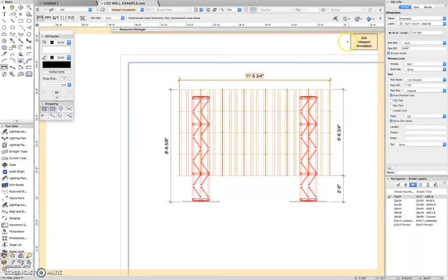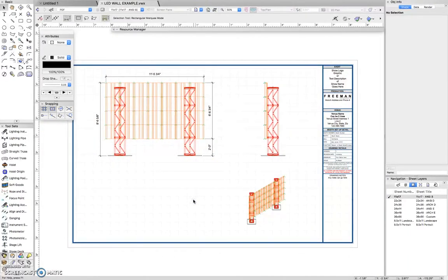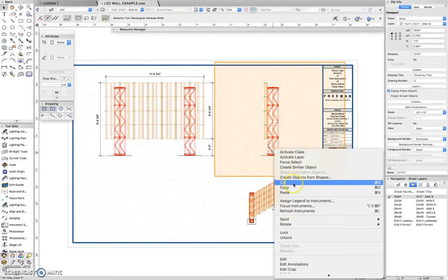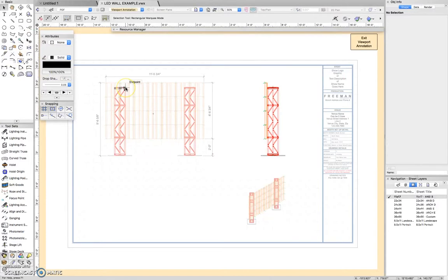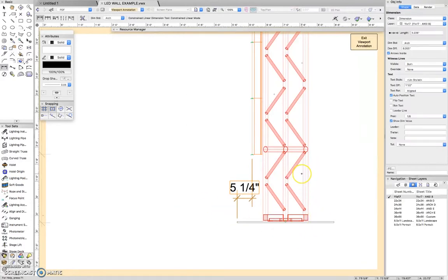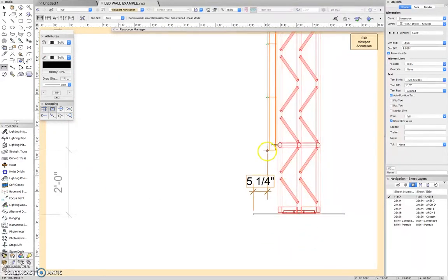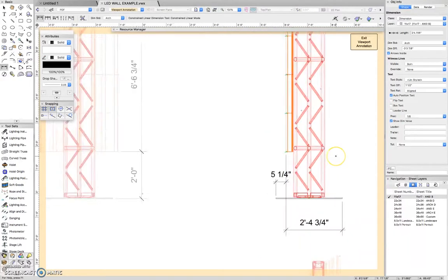So, ta-da. Hit exit, and look, our viewport is now nicely noted. You could do it on this one too. Edit annotations, hit the N button, and you can show, hey, looky here, the base plate sticks forward 5 inches, because people like to know that. Or you could go from the front of the wall to the back of the base plate, so if they build a structure, we need at least 3 feet of depth, stuff like that.